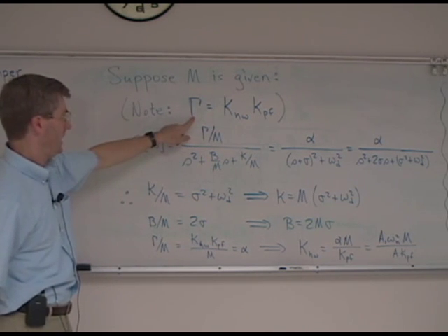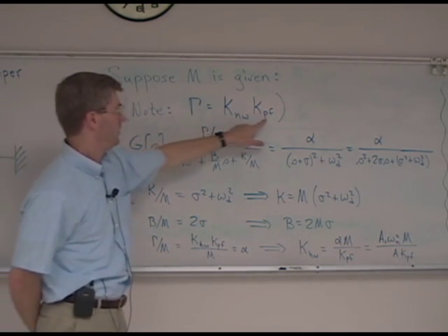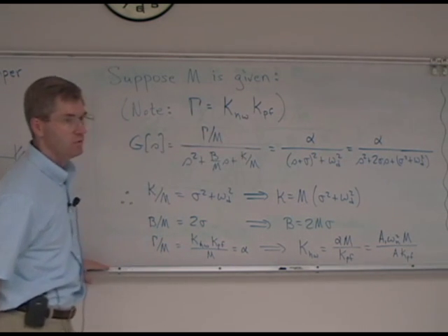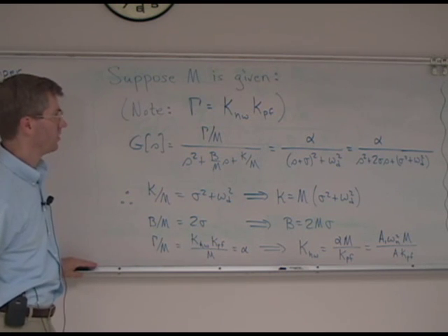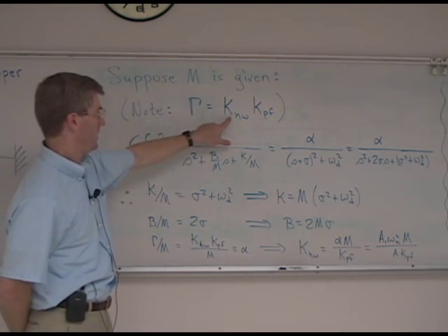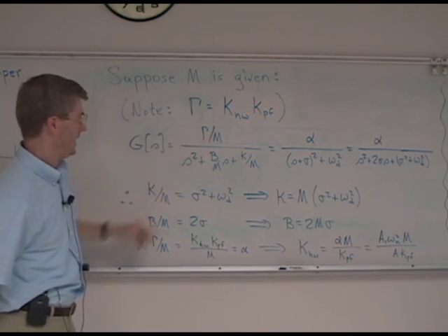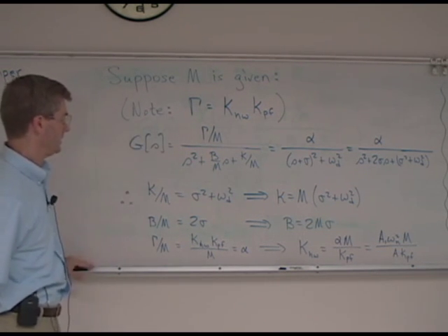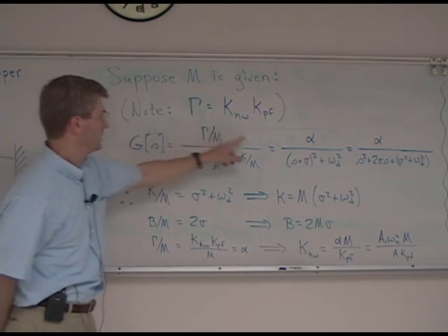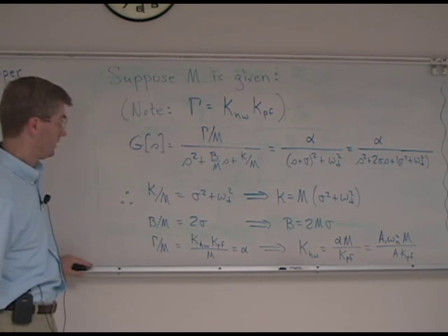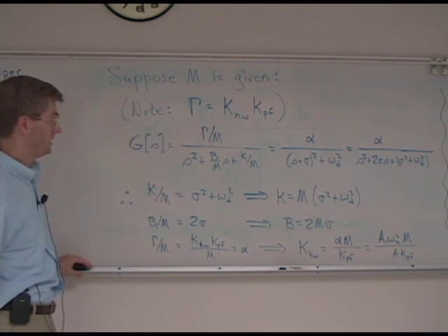If we know that gamma, the gain factor, is a combination of K sub PF and K hardware, K sub PF you will assign in your software, we will then be able to find K hardware from this gamma value in our G of s transfer function. This is the transfer function that we started with from our physical modeling of the mass spring damper system.